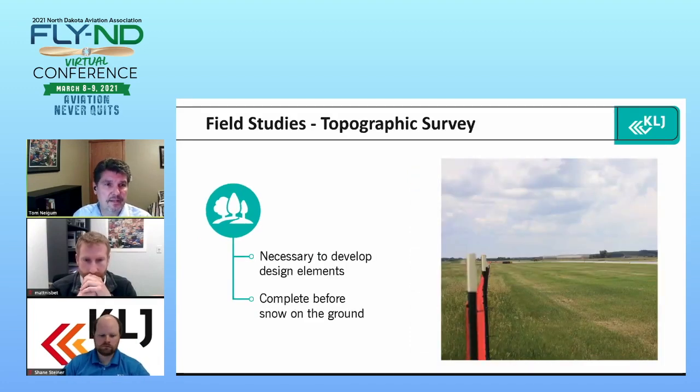So with the topographic survey, really what this consultant's trying to do is gather the survey data for the area that the design is going to occur, if they haven't done so already. So they'll want to get out there and get that surveyed as soon as they can in the fall, and really try to get that completed before the snow's on the ground. Much easier to pick up inlets and manholes and, you know, some of the infrastructure that's really flat on the ground if there's no snow on the ground. So want to get going on that.